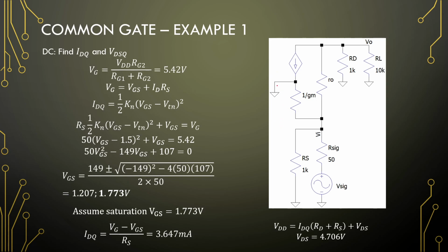So I'm drawing this as a 0 point because we will be seeing 1 over gm when looking into our amplifier. And if this is a ground, it is in parallel with our RS value down here. The output impedance will be these two resistors when looking in at the output. So very similar to that of our common source amplifier.